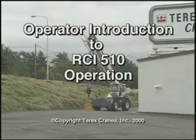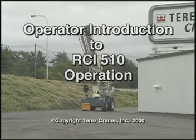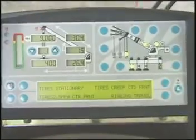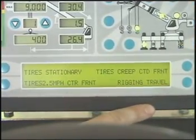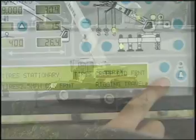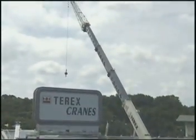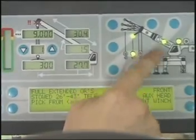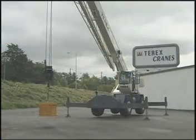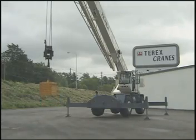The RCI510 provides the operator an indication of the allowable load in a given configuration, the actual load on the crane, boom length, boom angle, radius, and warnings of unsafe conditions. We'll start with an overview of the display screen, then use several scenarios to illustrate a variety of crane setups. We will then take you through the steps necessary to program the RCI510 for that particular setup.